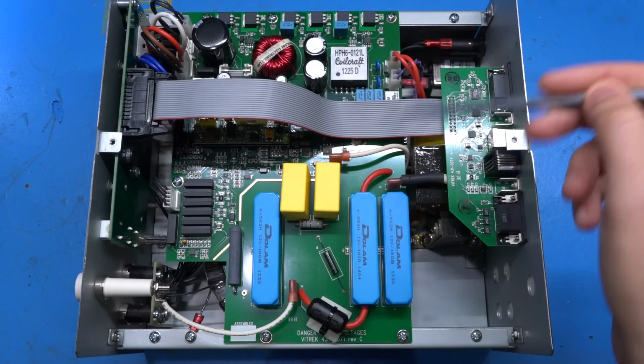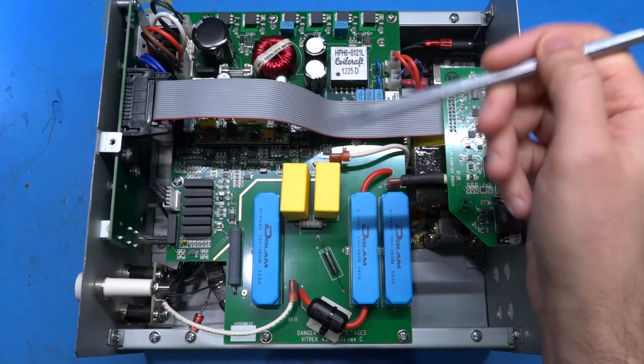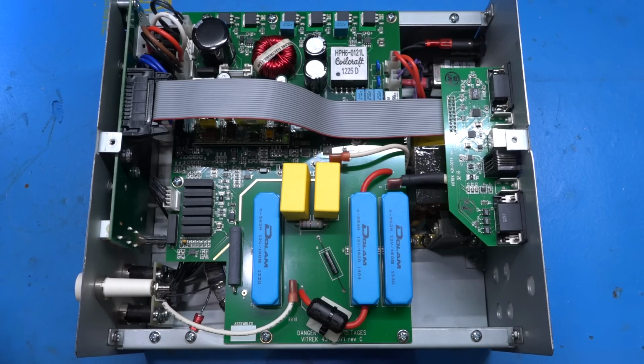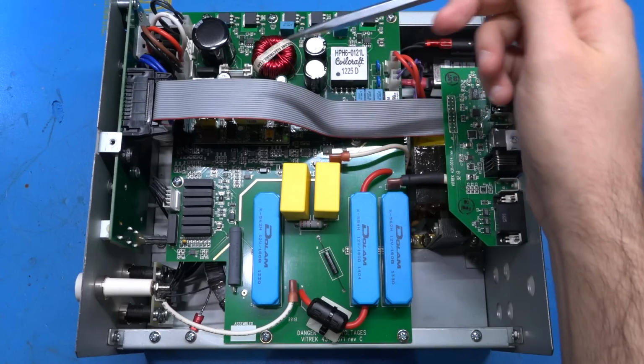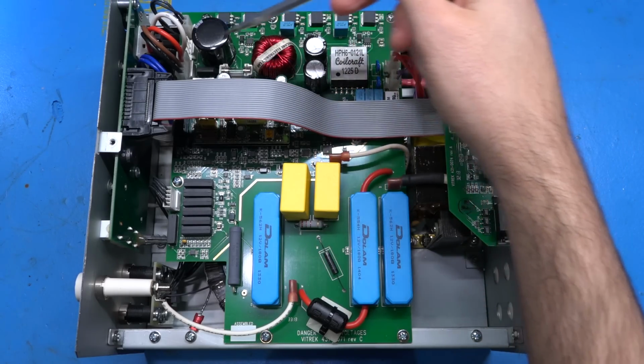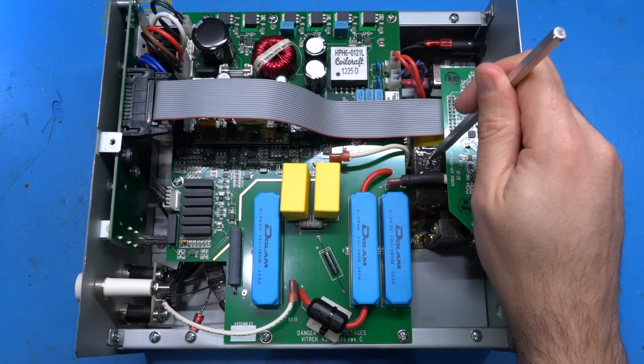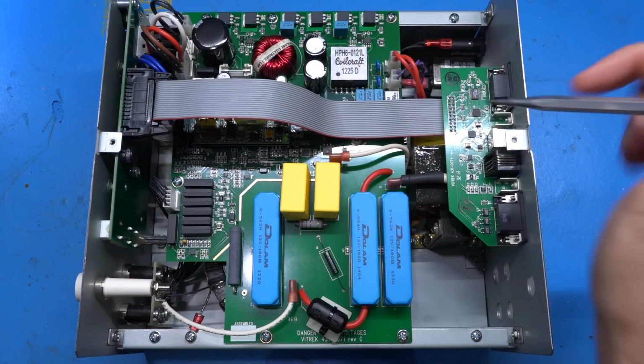Underneath this main PCB are a few toroidal transformers that provide the energy for the final transformer as well as for the ground testing that this instrument also has. Over here we have a DC-DC converter for most likely just the electronics, and we have the driving circuitry through these purple wires that drive the high voltage transformer here. This big wire that's coming out, that's the high voltage output.